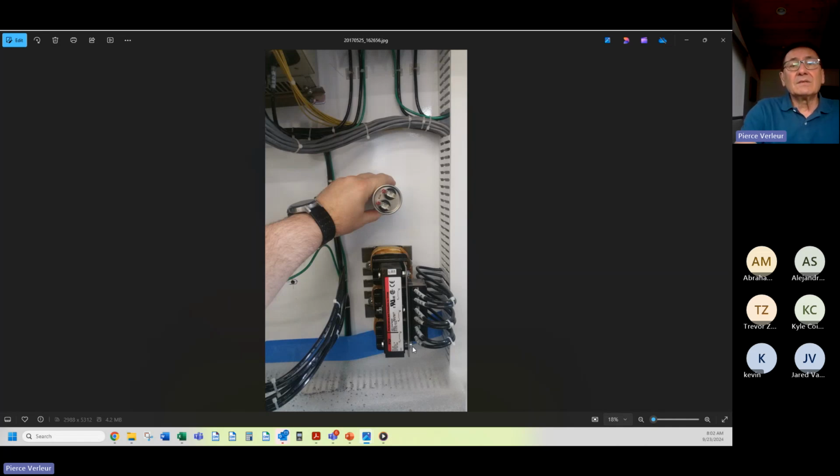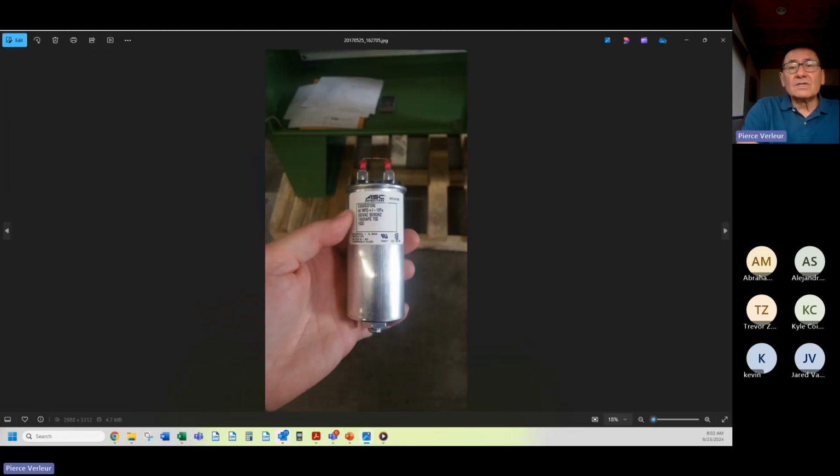When we removed the capacitor, the problem went away and the drive did not OC trip. So that's one of the reasons why long lead lengths can affect you. And they didn't use inverter duty cable like we had specified. So the whole tank circuit changed.